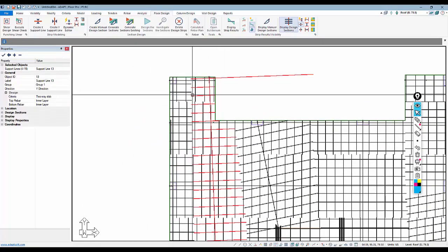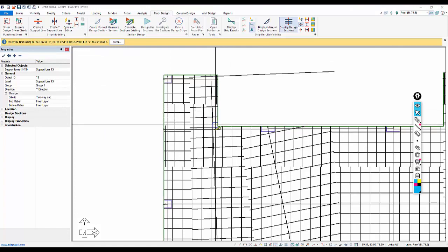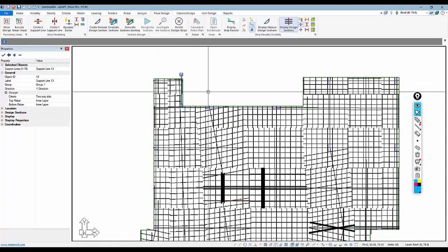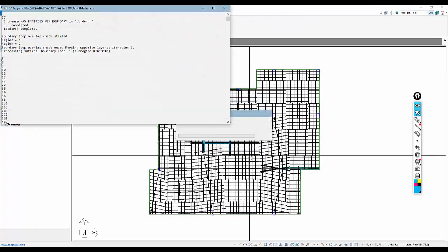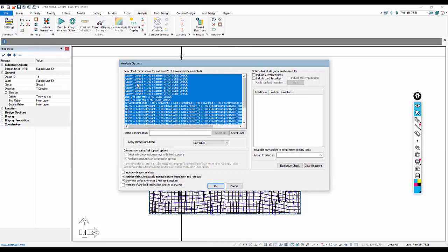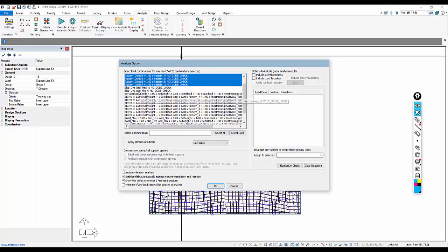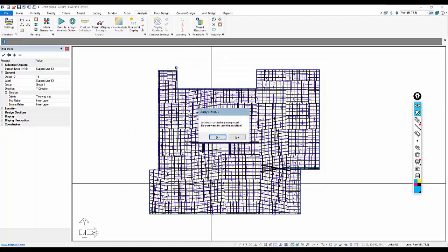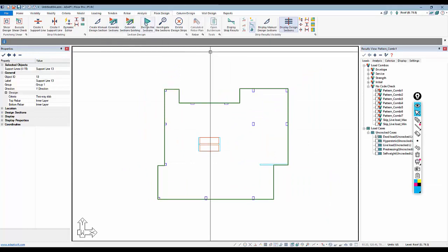This cut is occurring outside of the slab, so if we add a Y direction splitter here, let's see if that cuts that off. Okay, so that just bounds that tributary to that line. We're going to go ahead and mesh the slab. We'll execute, and you'll notice these patterns are actually stored here. This is done automatically so that we solve the patterns and we can superimpose them into the load combinations. So we want to make sure we solve these patterns with the combinations. Okay, and then we'll go ahead and design the sections.